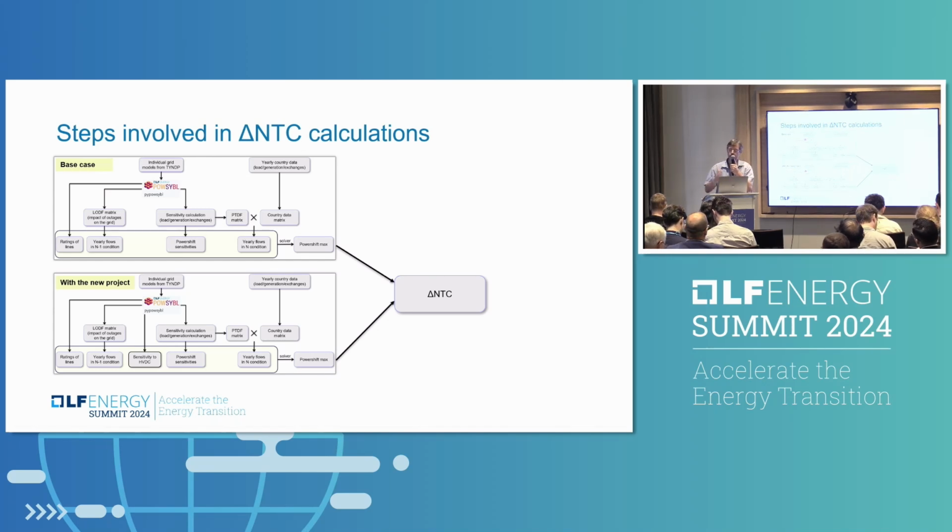Yes, sure. This is typically the case when you have, for example, a new interconnection project. When the new interconnection project is just a reconductoring of the line, that means that you will increase the thermal limit of your line, and then the difference in terms of power shift will appear in the ΔNTC calculation.